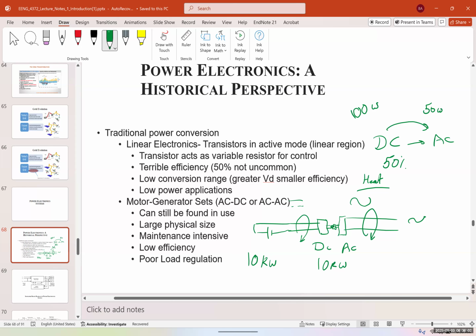What does this mean? If you have a generator that is connected to a load, imagine you have a heater on the other side, and you suddenly turn on the heater, you have a switch, you turn it on. When you have load on the generator, what happens when you suddenly switch it on? It's going to put pressure on the generator, and it's going to immediately reduce the torque because it has to work harder to generate the power.